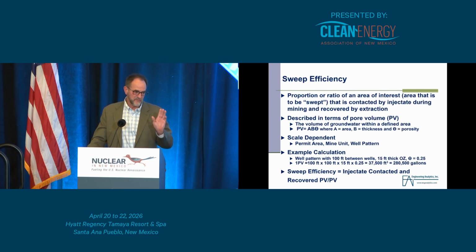This is one of my favorite topics, maybe because it's pretty poorly understood, I think, even within the industry sometimes: sweep efficiency. Sweep efficiency really is just the proportion of an area to be swept or mined that is contacted by injectate and then recovered at the extraction well, over the whole area of interest.